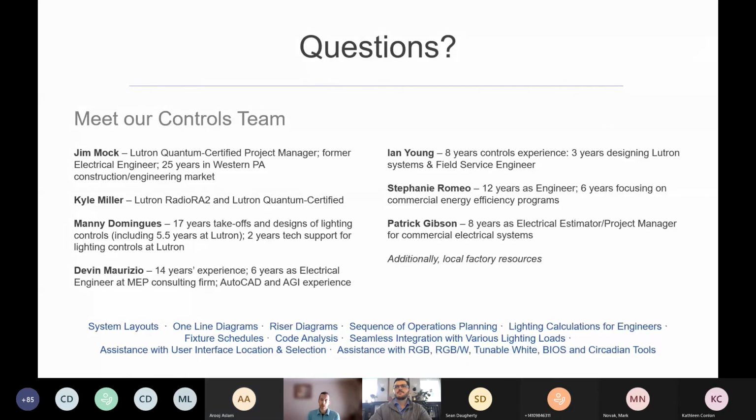So if you have a generator on your job, a lot of times they do not put batteries into the fixtures, and they use the emergency source from the generator, just because it's another item that needs to be checked inside the fixture with the battery, to be tested to make sure it is still working, things of that nature. Okay, cool. Thank you.